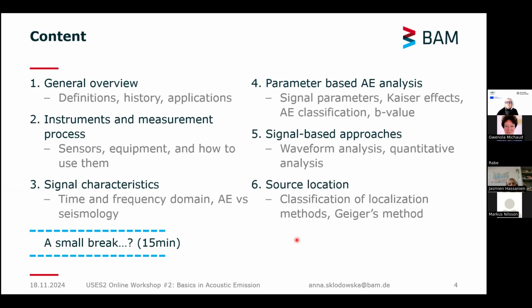Then we're going to also scratch a little bit of another big topic, that is source localization. I'll give you a general overview of the methods that are used and talk a little bit more about the commonly used one, called Geiger's method. And with this, I will sum up, give some conclusions and a small outlook: what are still interesting hot topics in terms of acoustic emission, which could be developed much more.